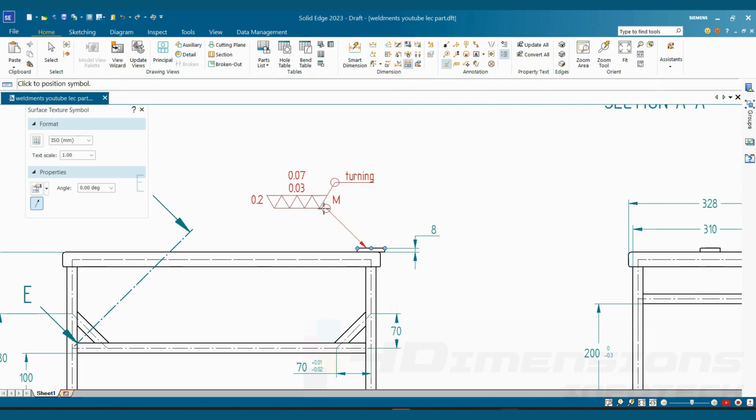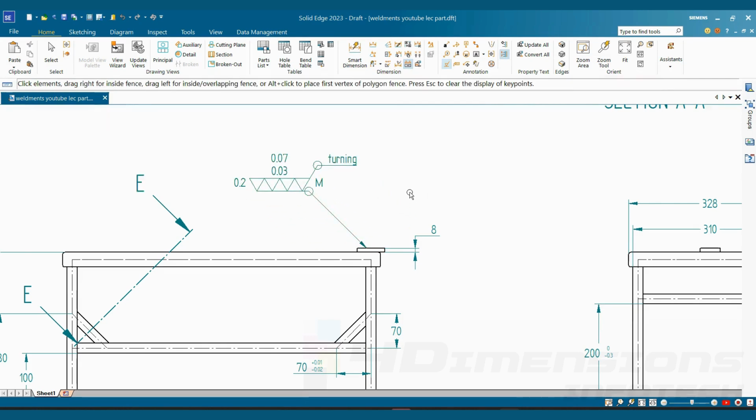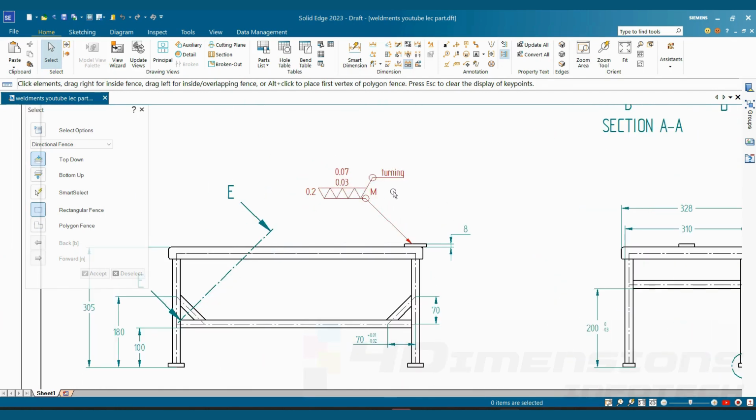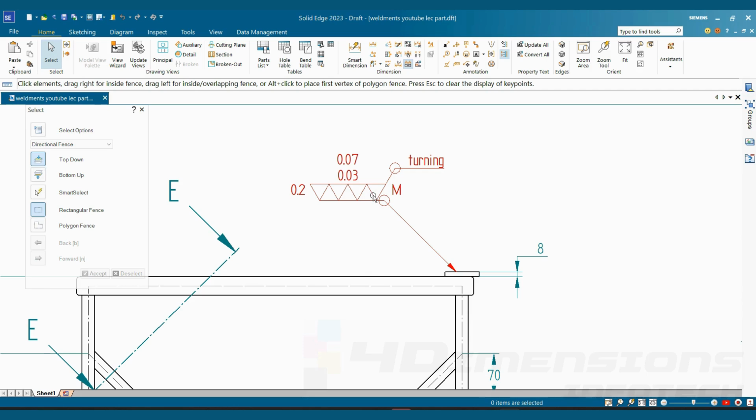Click on the surface and place the symbol where required. So in this way you can show the surface finish symbol here. This is the allowance value. This is the maximum and minimum roughness value. Machining process is turning. All around means the complete surface is to be machined. And the lay direction will be multi-directional, meaning the pattern produced will be multi-directional on the surface while removing material. So this is the explanation for this icon. The number of triangles represents the surface finish, how smooth the surface finish should be.